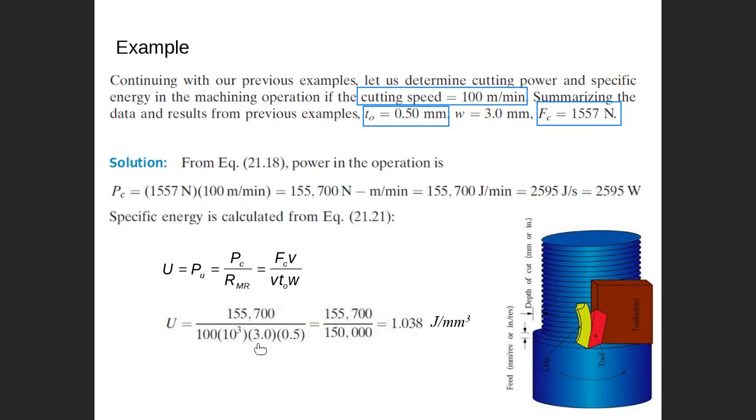The value of U, the specific power, that needs to be multiplied by the correction factor is the one you obtain from that table. I'm highlighting this one, please be careful. The one you obtain from the table, in case of TO bigger than 0.25, in this case you need to use a correction factor. This is the only case.